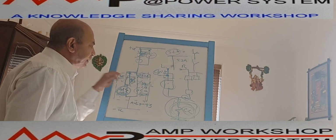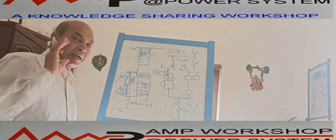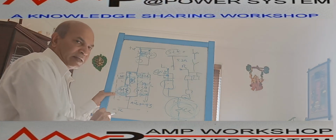But if you put in another anti-pumping relay, this 94 relay contact over here, once the breaker is closed, what is required? Once the breaker is closed, the anti-pumping relay should maintain energization. It should not drop. So the moment the breaker is closed, through the breaker auxiliary contact, the anti-pumping relay is energized.